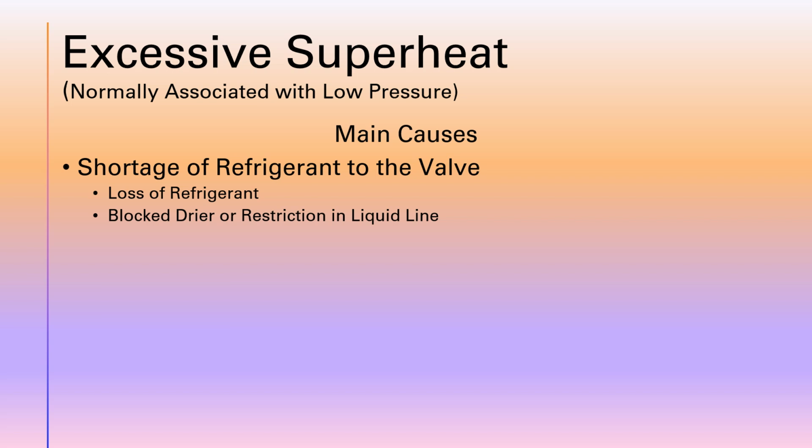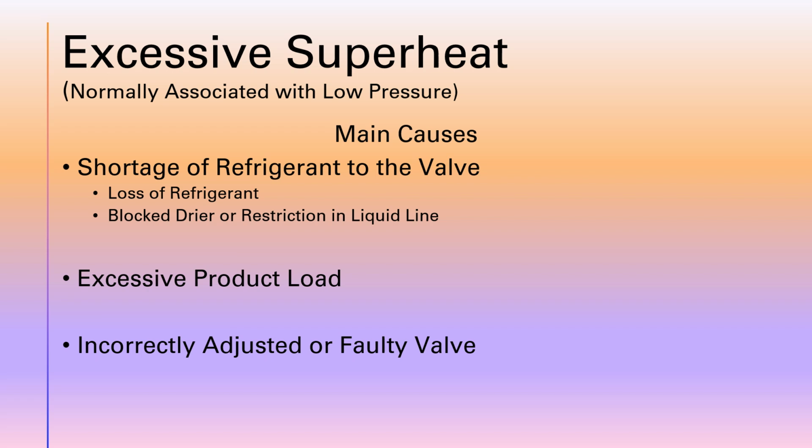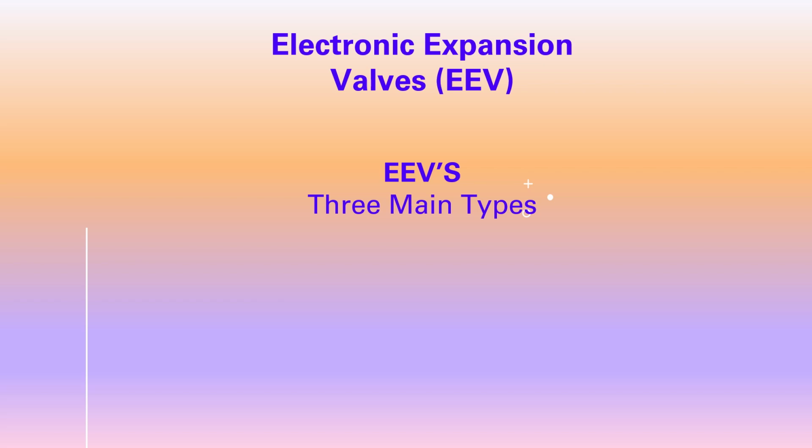A blocked dryer or restriction in the liquid line, and excessive product load, or an incorrectly adjusted or faulty valve.